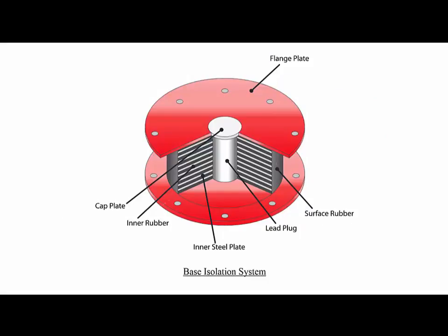The base isolation devices are made of layers of high yield steel plate and rubber that are very rigid and are put together in layers. And then in the center we have a lead core. The lead can dissipate the energy of the earthquake through lateral deformation and turn it into heat, while the rubber and steel plate become very rigid and can take the gravity load very easily.